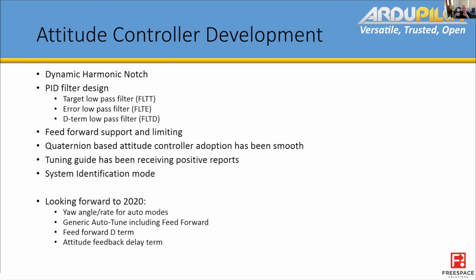The EKF doesn't have the low pass filter or the harmonic filter going on the data it consumes and then works out what the angle is. So that angle is effectively unfiltered, and there's a bunch of reasons for that, but pretty much the EKF likes raw data, because then everything makes sense. If you start removing part of that data, then all of a sudden things don't make as much sense. Bill, I'm sure we could go into that a lot in the next talk.